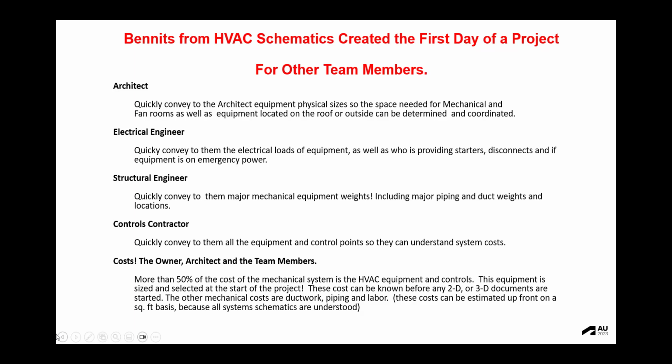You can start a wizard by going in and entering this, so much CFM per square foot, and start sizing equipment. Or once your loads are done, then you can import those loads as we talked about and build the system and select the product from the loads.